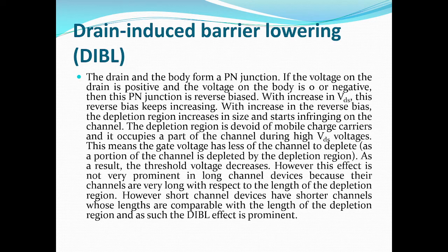The short channel devices have shorter channels whose lengths are comparable with the length of the depletion region, so they have the DIBL effect as prominent. In ideal characteristics, we assume the channel length is so long that we ignore these parameters. But in short channel devices, the DIBL effect is also high.